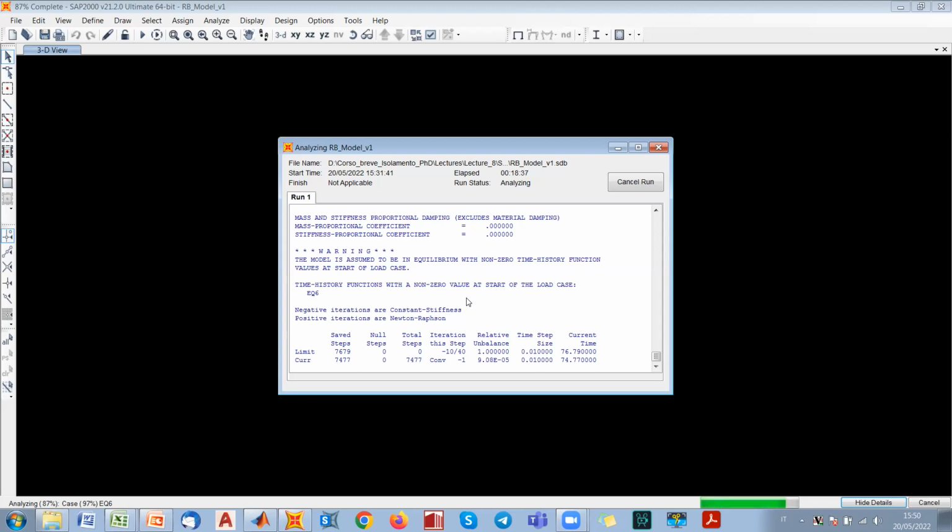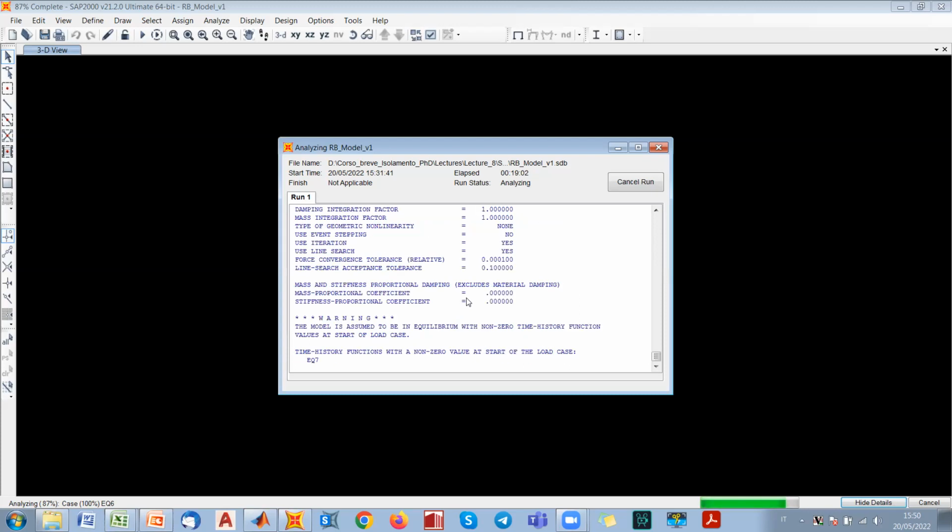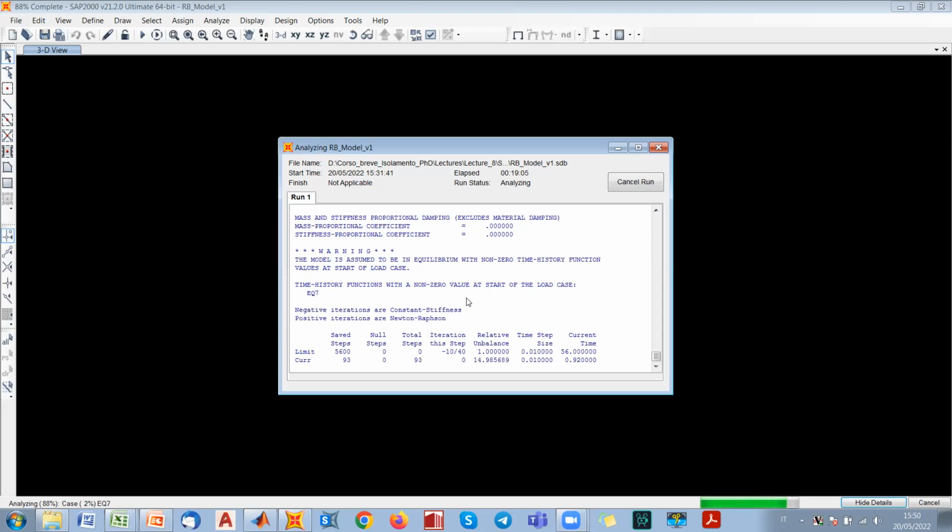I see, thank you. Do you know if there's any reference for the maximum allowable residual displacement after an event for the isolator, for it not to require some recentering or replacement? Is there something on that? Well, I actually don't know if there is a numerical value in the standard code, a clear prescription of the maximum allowance of the residual displacement. So I think it is the structural engineer who has to say if that value is small enough to not recenter all the buildings which have been displaced. I see, perfect, thank you.